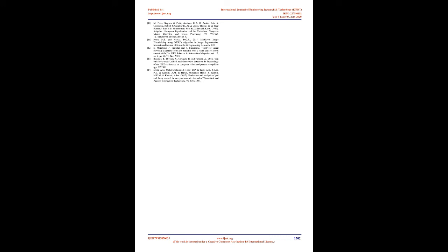Search. Search mode will be activated if no tasks are pending and no paths are visible to the AUV. The AUV will start to navigate at predefined paths designed to get the vehicle back on track. This node will also be responsible to navigate the vehicle to the desired location of the next task. BossNav. The function of the node is to receive three-dimensional coordinates and communicate with the convert node to evaluate precise thruster values.